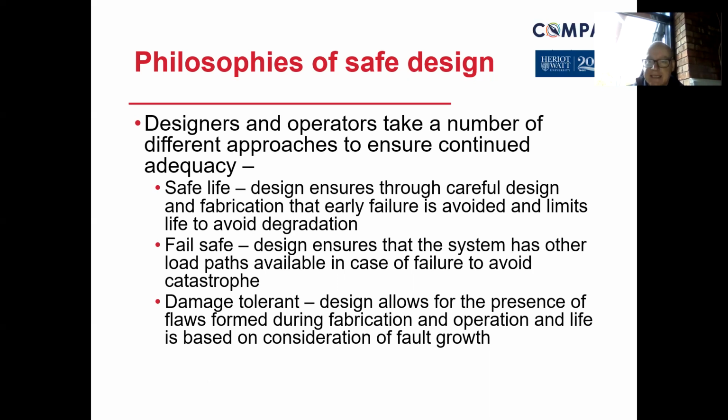Design ensures that the system has other load paths available in case of a failure, a backup plan to avoid catastrophe. So if something goes wrong, perhaps mechanically, a chock comes in, so the press doesn't come down all the way. So perhaps you lose energy, and as a result of losing energy, it kicks in a pressure switch. The pressure switch releases, and it puts the chock in position, so the press can't come down and squash someone or damage property underneath. Those kind of things. Fails in a safe state.